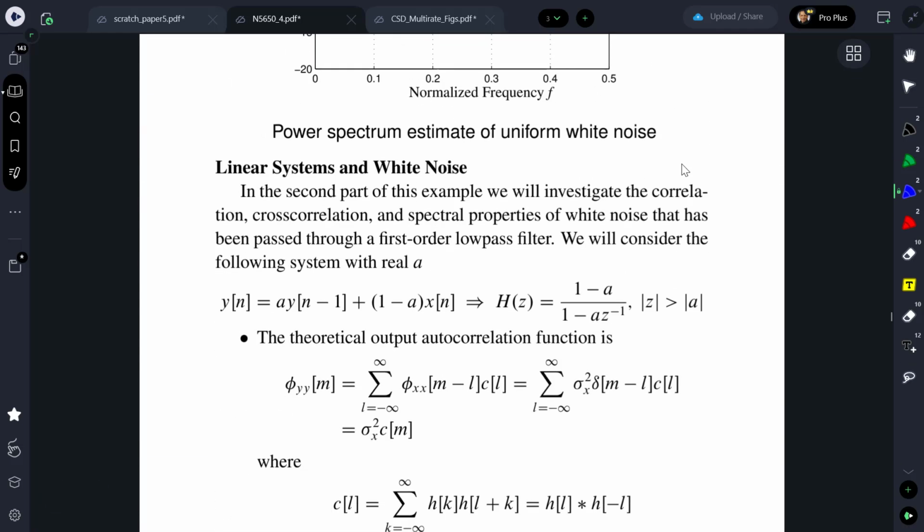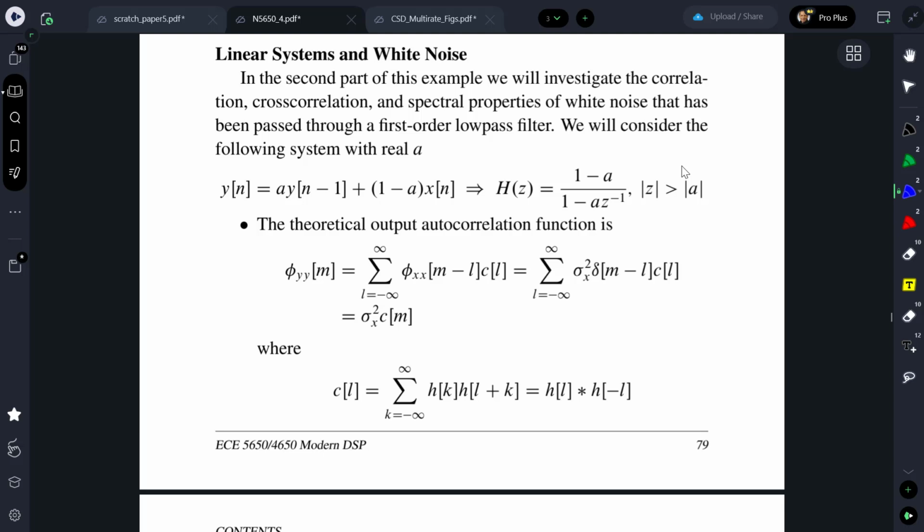And now we're going to go through and send our signal through a first-order low-pass filter, and it's a low-pass filter of this form. It has unity DC gain. And now we want to analytically model, and this shows up in the second homework problem of set 5. We've got this sort of a filter, and we want to find out what this autocorrelation between the impulse responses is. That's what the CL function is.